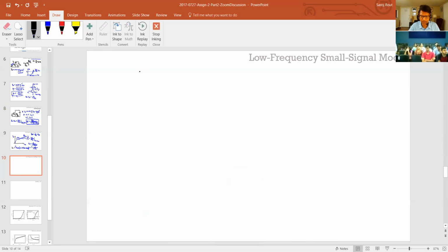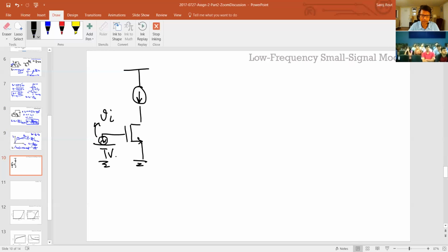So if I construct the small signal model now, maybe I'll also take this moment to say, you're all probably familiar, but I'll just repeat it. For example, we took that common source amplifier, right? And we had some gate to source voltage and some overlapping small signal voltage VI here, VGS, and then a current source IB, which resulted in some VDS.